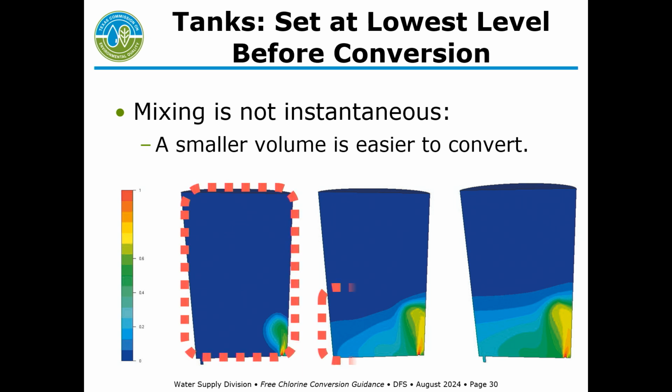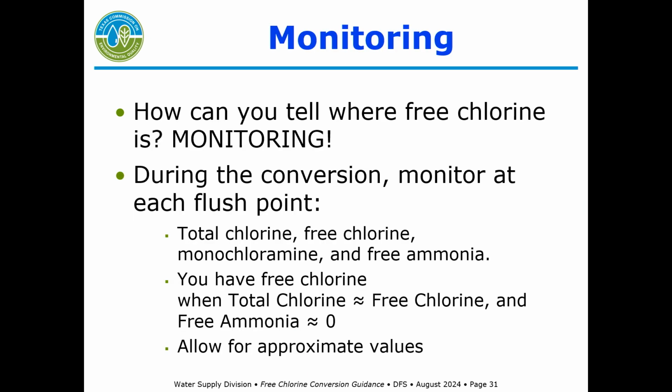But a smaller volume is actually easier to convert. If you only had the tank half full, it would convert over to free chlorine a lot faster. That's what we're trying to illustrate there. So, talk about monitoring. How can you tell where the free chlorine is?